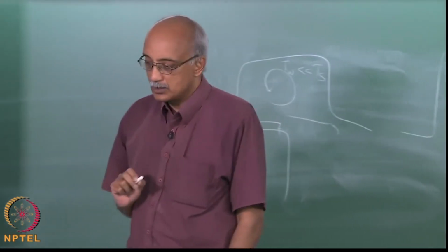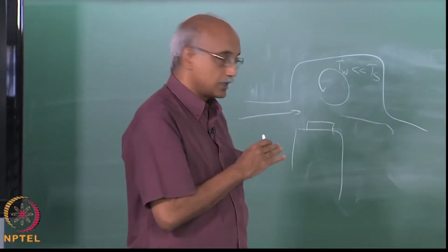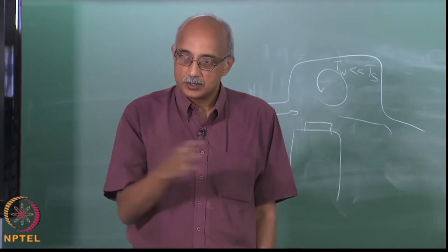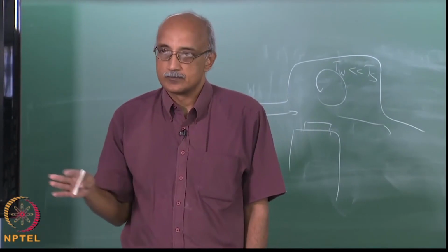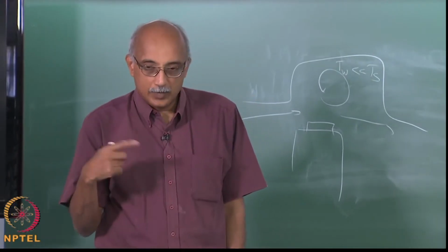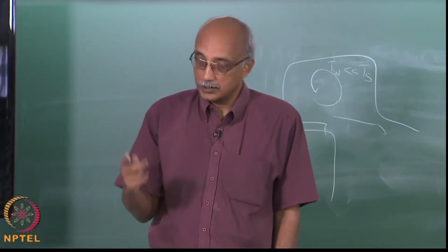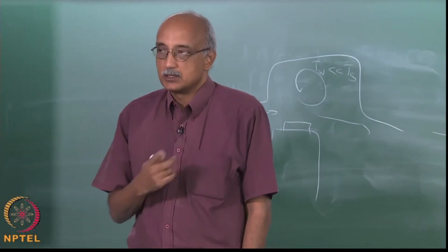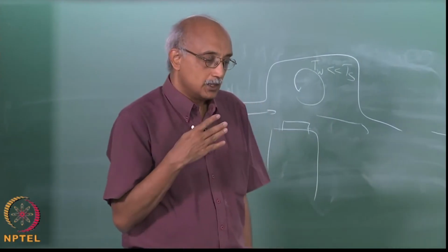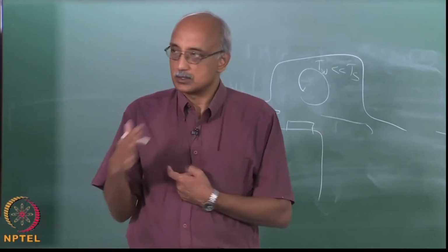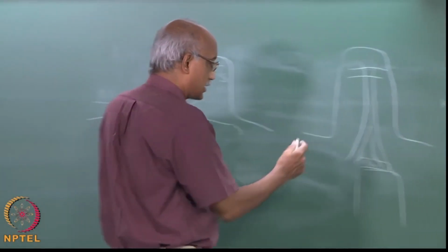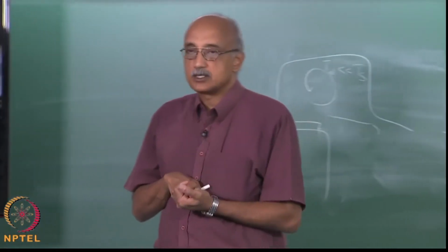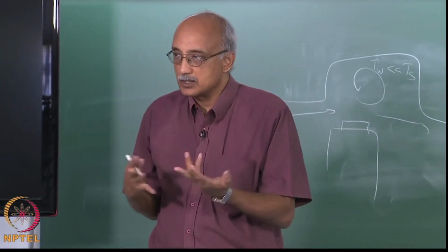The thing that we want to ensure is that the residence time of the reacting species adjacent to the substrate is kept uniform along the length of the substrate. And so, you do have to do some CFD modeling to understand how flow is going to happen in the vicinity of the substrate. So, again, in terms of analysis and controls, the focus in a stagnation point reactor is only around this region. So, that reduces the complexity of the design and therefore, the cost.